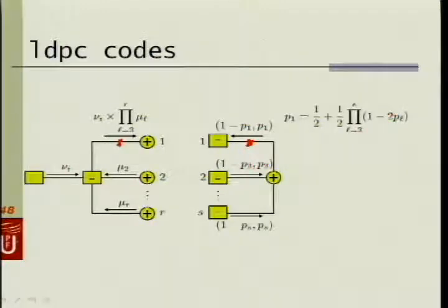We do this calculation because each one of these two steps, calculation of this guy and calculation of this guy, are simply an implementation of the basic step of the sum product algorithm applied to these two simple functions, the repetition function and the parity check node function. Okay, so that's all we need to know to decode a low-density parity check code.